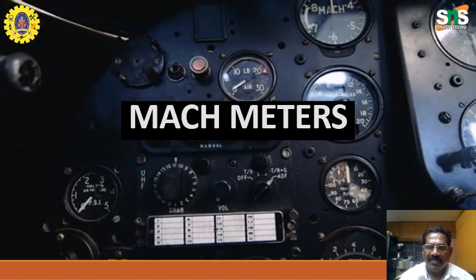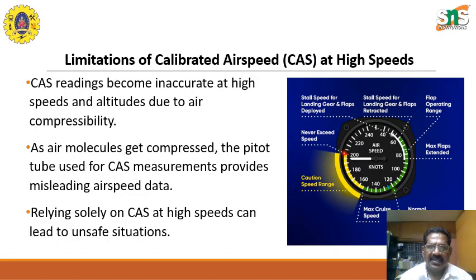Now, in this video, we'll talk about the Mach meters. What are Mach meters and the limitations of calibrated airspeed? What really happens at high speed? The calibrated airspeed becomes inaccurate at high speeds and altitudes due to air compressibility. As the air molecules get compressed, the pitot tube used for the CAS measurement provides misleading airspeed data. Relying solely on the calibrated airspeed at high speeds can lead to unsafe situations.